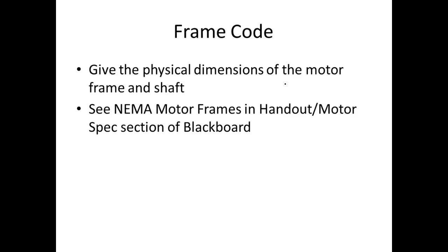This is the motor frame handout. This is up in the motor spec station if you wanted to go look at it. We're not going to go up there. So that's one thing: if you're going to buy a motor, you don't have to buy it from the original manufacturer. You just have to get it with the same electrical characteristics and the same mechanical characteristics, and you can replace that motor from anybody. A lot of people don't understand that. Just about everything about a motor is a NEMA standard. So it's going to have a code letter on there.